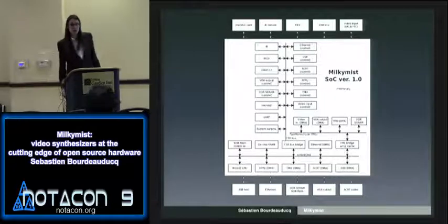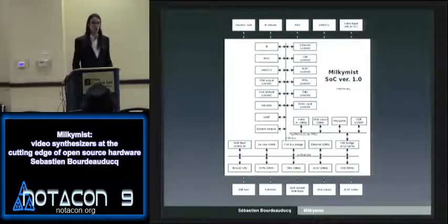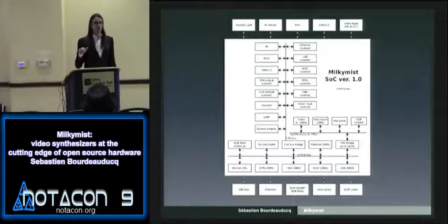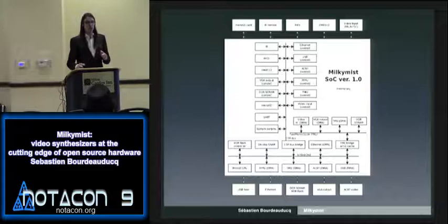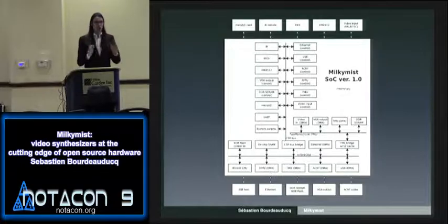Yeah, NTSC worked as well, but actually the BT656 standard is transparent to these standards. The decoding between NTSC or PAL or SECAM is happening before the BT656, and then it doesn't really matter if you have PAL, SECAM, or NTSC. There are some differences because the refresh rate is not the same, but the basic BT656 protocol is exactly the same, with just small differences in timings that are very easy to take care of.